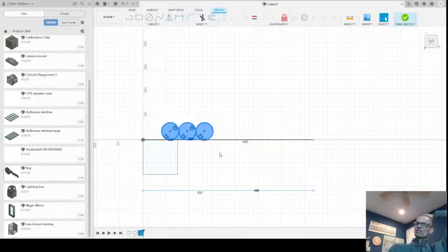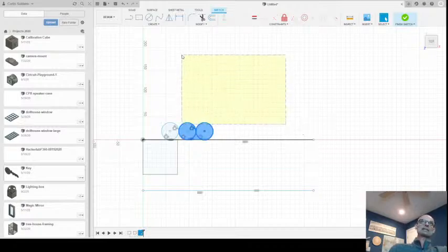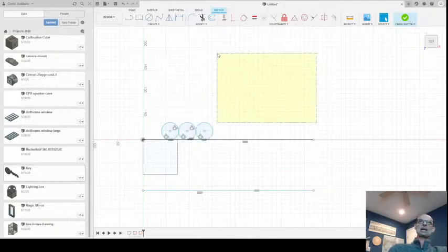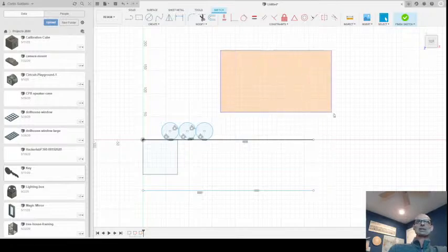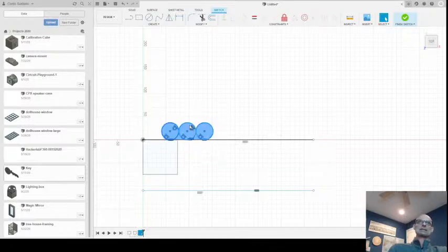I don't know if you noticed what I just did there. I don't know how often this is talked about. I'm not sure where I got it from. But left click and drag group selection is different than right click and drag. This is left click and drag, and this is right click and drag. Now you'll notice one is yellow and has a dashed line around the bounding box. The other one has a solid line and is orange inside. And the way those behave is if I use the right click and drag, it selects just the objects that are fully covered by my selection.